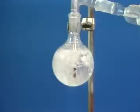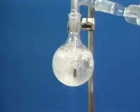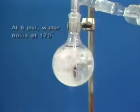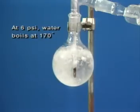Vacuum tower operation is based on the fact that pressure affects the boiling temperature of a liquid. For example, water boils at 212 degrees Fahrenheit at standard atmospheric pressure, which is 14.7 pounds per square inch, or psi, at sea level. If pressure is decreased to 6 psi, water boils at 170 degrees Fahrenheit. When the pressure inside a tower is reduced, liquids are vaporized at lower temperatures. This process is referred to as vacuum distillation.